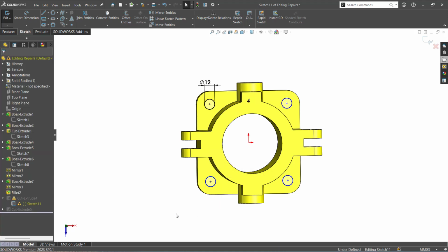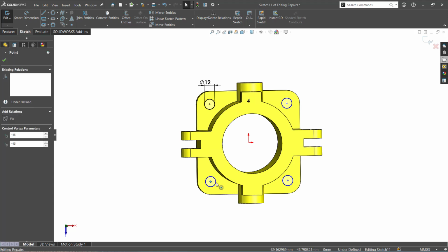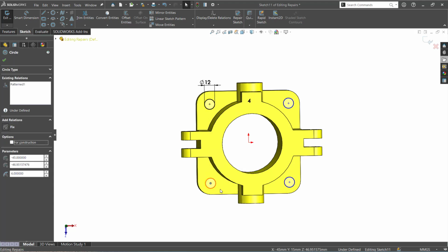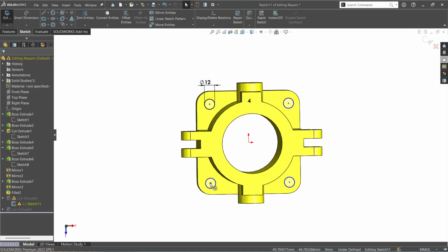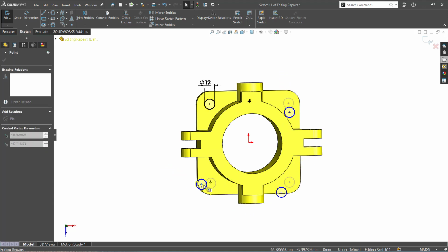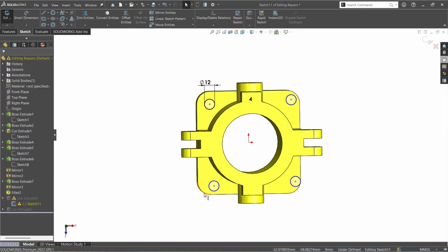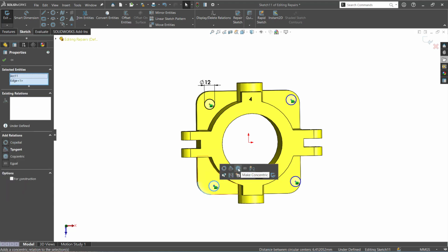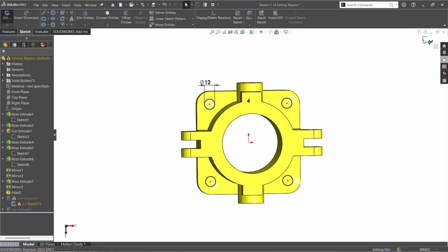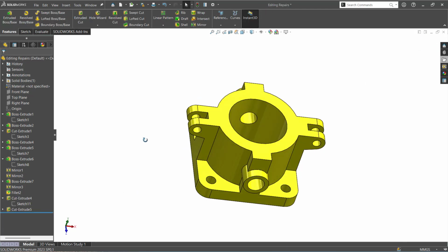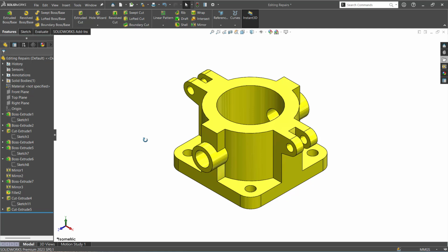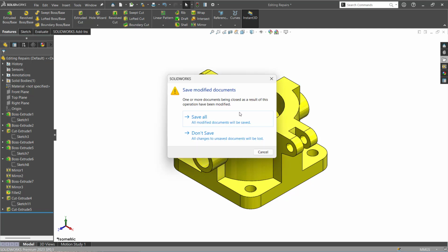We make it equal with the Equal relation first. Because there's no issue, I can drag it now, it is moving like this. So what I can do is again assign the equal relation for these two. Then everything is fixed. Any doubts? No. Okay, I'll just close this.